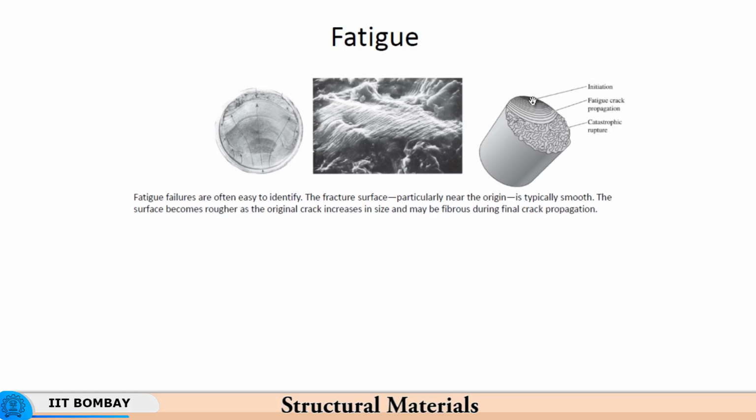So these wave patterns are created on the sand, similar to what happens over here. So here there is an origin of the crack. The crack propagates a little in one cycle, it remains there, then depending on the load it propagates further. Now we have seen during our discussion on fracture that the crack propagates depending on the degree of stress concentration. If the degree of stress concentration is high, the probability of the crack propagating will be that much higher.